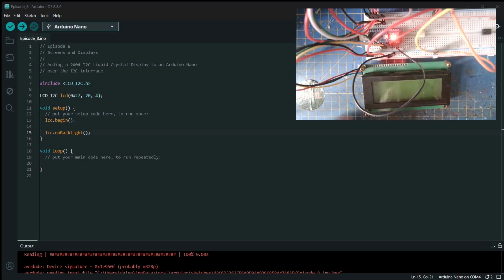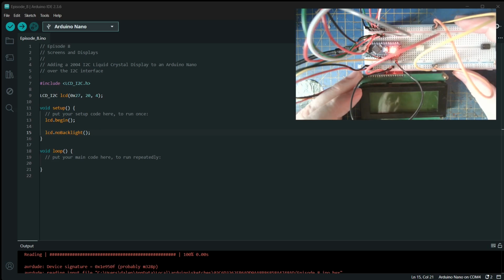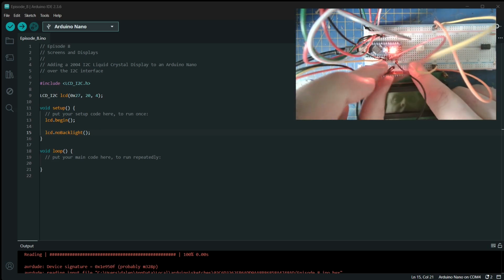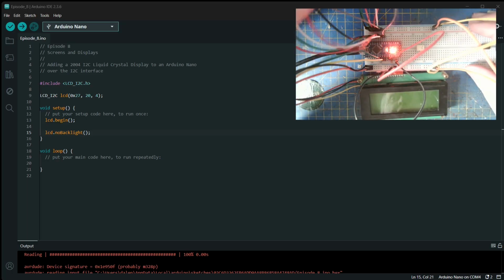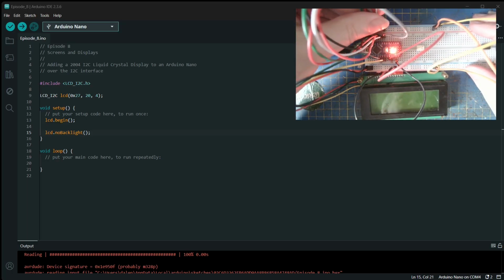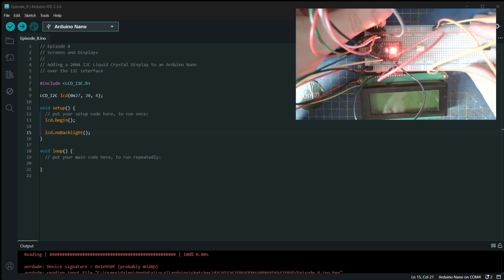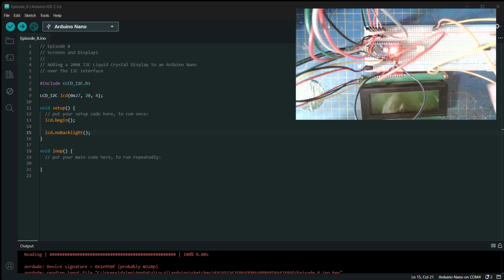Okay, right. I've made a few slight changes to the board. Firstly, we're now using the power strip, top and bottom. These wires are just bridging the power strips. Over here, I've got 6 wires connected from D4 through to D9, which I'm going to use as my inputs. I want the screen to show me the outputs. And then we're going to do a little bit of processing with them.